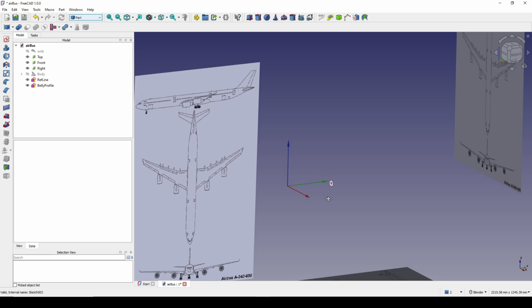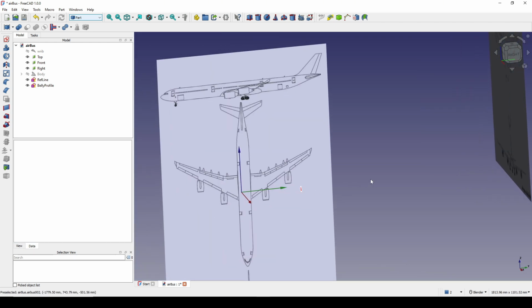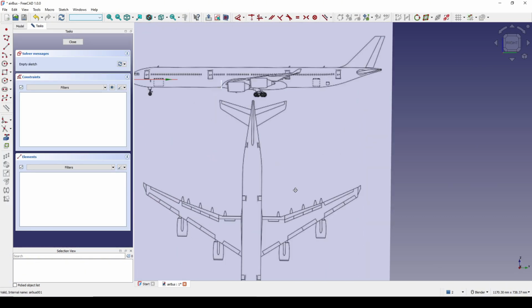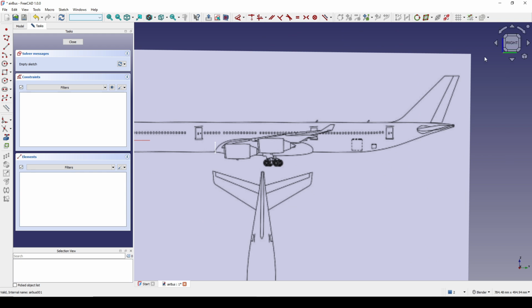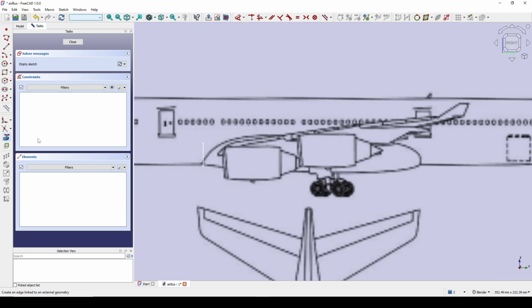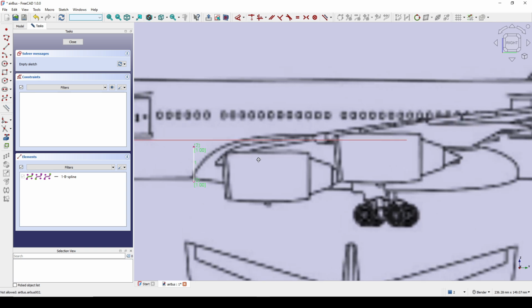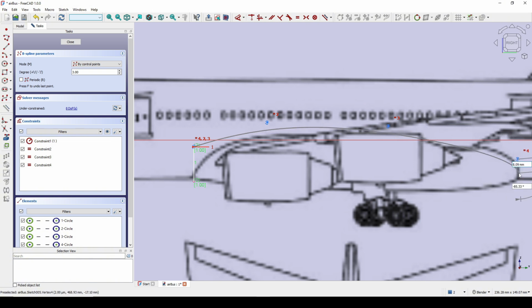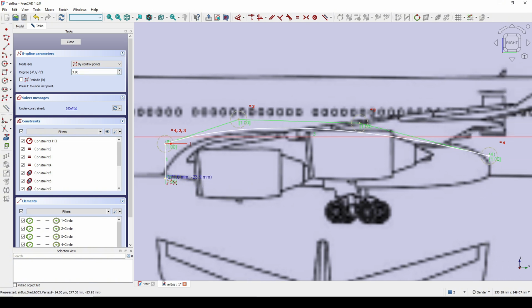Now I can create a hole curve for the right view. I create a new sketch in the right view. And I will reference this line. And I will create a B-spline and we start from here. I put 1 point, 2 points up here and the last point in here. Doing the same down here. 1, 2, 3, and 4.